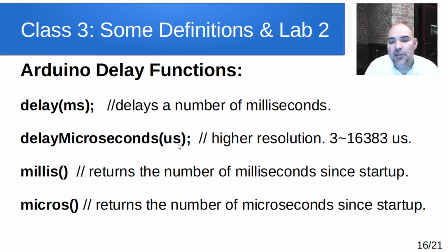But above that, you should be able to get microsecond resolution out of it. There's also a way to get the amount of time since startup. There's a function called millis, which returns the number of milliseconds since the board was last reset or powered up. And there's one called micros, which returns the number of microseconds since startup.